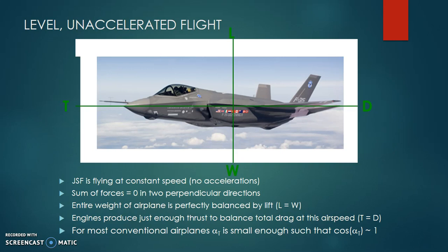Now, let's revisit our standard cruise mode equation, where we said that in cruise mode, this aircraft is subjected to a lift which is exactly equal to weight. That's why it maintains its constant altitude profile. There is no external force in this direction. The forward thrust is exactly the same as the drag experienced by this object because of its aerodynamic shape passing through air as a fluid. Because every object, as we know from fluid mechanics, when in motion in a fluid, will experience certain friction, which is nothing but drag.